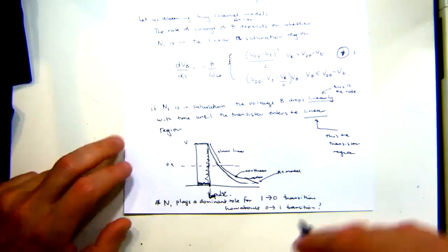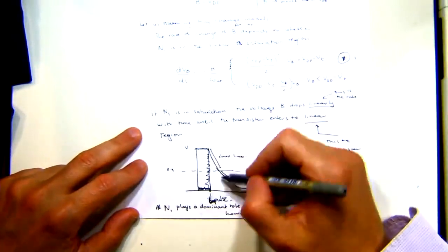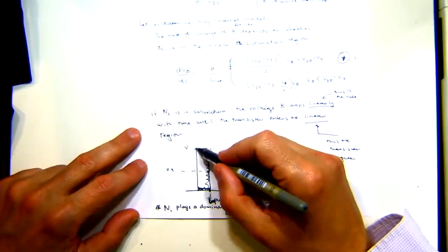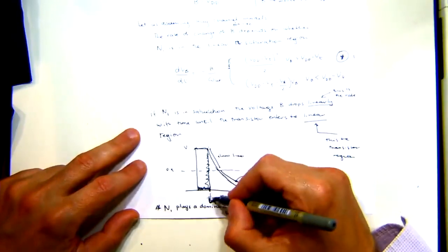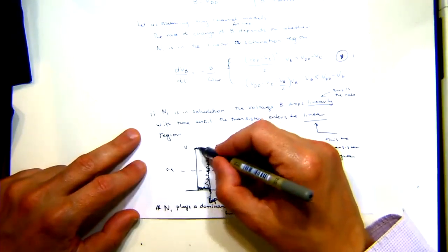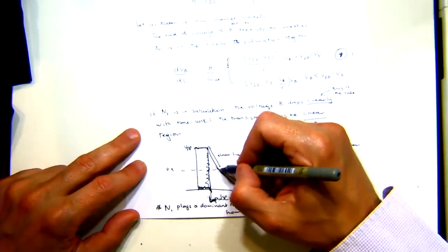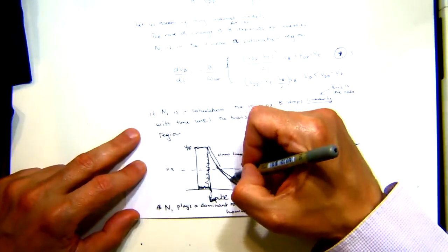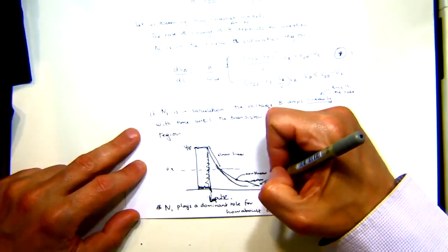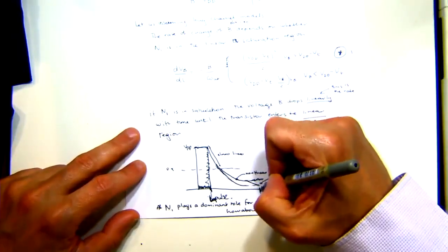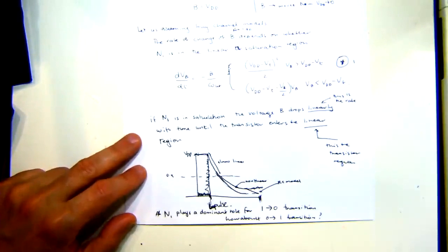Okay, so as Will just pointed out, I had done this, which is incorrect, because this is time equals 0, so the voltage is at 1, or VDD. We switch, and then this is what happens to the output voltage. This is how it's decaying down to 0. This is a problem when you don't copy out of the book.